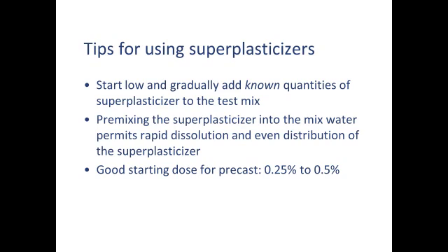A good tip is to pre-mix your super plasticizer in your mix water before you add the mix water to your ingredients, and then add the mix water to the aggregates, get that well mixed, and then add your cement last. The worst thing to do is to have all the dry ingredients mixed together, add your water, and then add the super plasticizer at the tail end where it's doing the least good. Their job is to help disperse things. That helps mixing. It helps get everything not only blended properly, but the admixture, the super plasticizer, the water reducer, whatever version you're using, starts working faster.